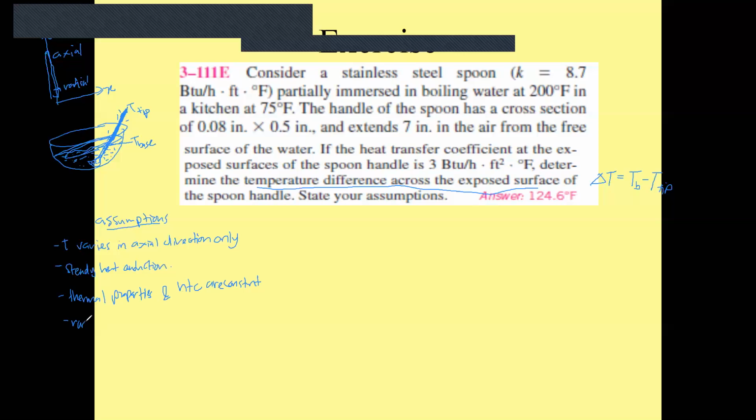either you can say radiation is neglected, or if you want to take it into account, you can say the heat transfer coefficient already includes the radiation, which means that you don't have to do radiation separately anymore because it's already been taken into account in this value here.